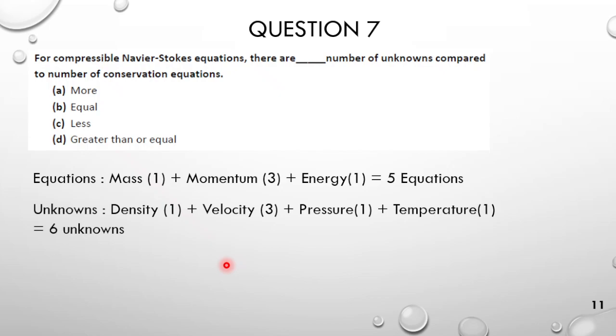So you have something called closure equations, which is the equation of state, wherein you relate pressure and temperature through the energy equation. Mainly you have P equal to rho c squared, for acoustic terms if you want to solve, or you have a relation between temperature and pressure using the ratio of specific heats. That comes in the equation of state.